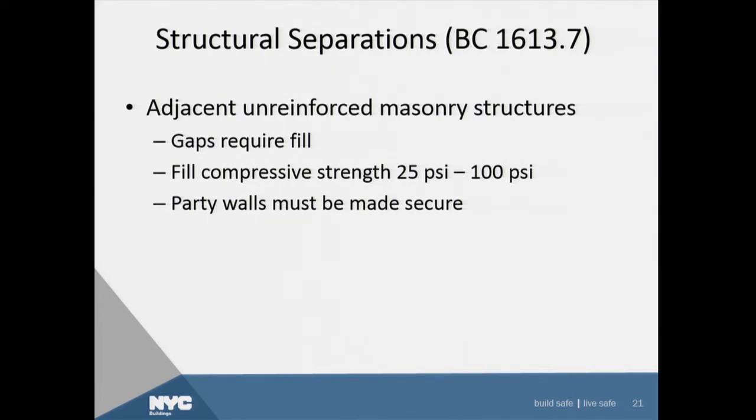But before putting up the new building, you have to plan for what you are going to do with that wall. It is part one owner's and part the other owner's, but that wall needs to be structurally braced. And there have been some situations where neither owner intended on laterally bracing that wall, which may mean you may have a 6-story unbraced, unreinforced masonry wall in place unless somebody does something about it. The code now clearly points out that the party doing the new construction has to address this.